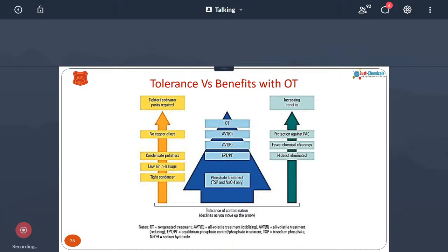And in the once-through cycle, we were getting iron at around 12 ppb to 13 ppb in our feed water systems. Then when we changed to oxidative treatment, those ppb levels came down below 2. So the corrosion which was occurring came down from 12 ppb, 13 ppb to 2 ppb. That is the change which has occurred in the steam water circuit.